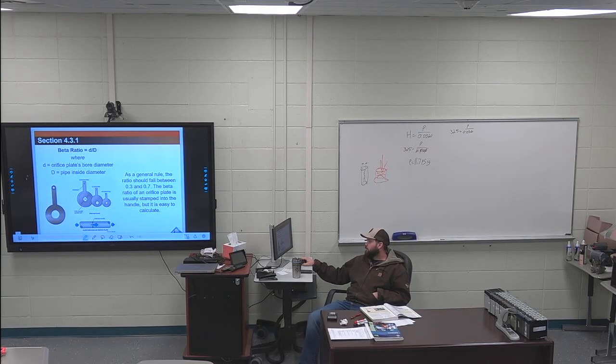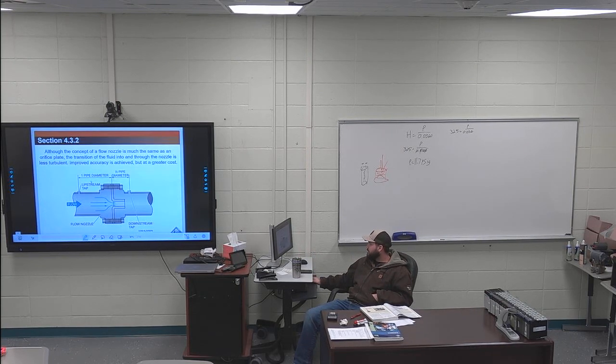So you take one of these orifice plates and you put it between two flanges, and you have a very, very known opening or orifice in this plate. Based on that, math can be done, like the square root, usually done inside a differential pressure transmitter. That should also reduce the exerted pressure from the other side.